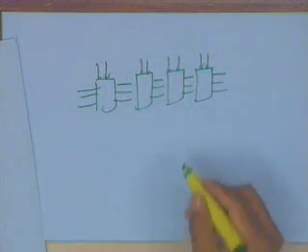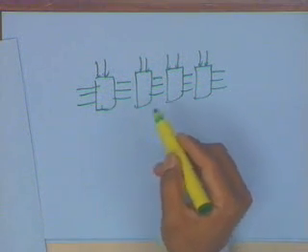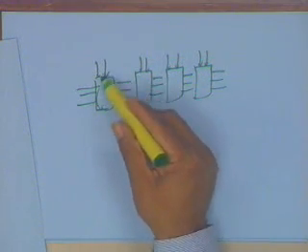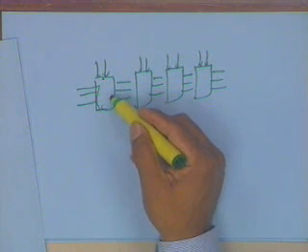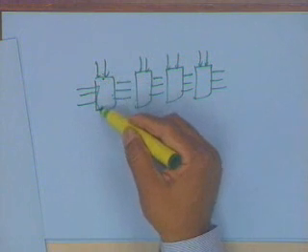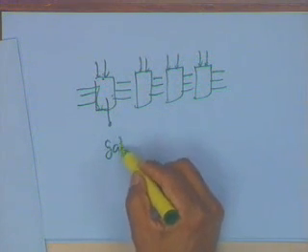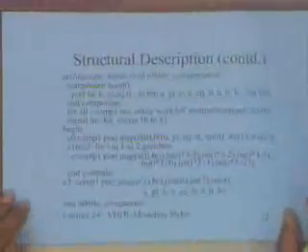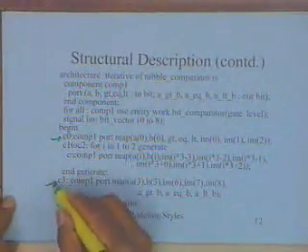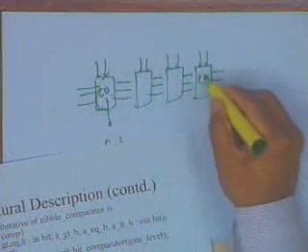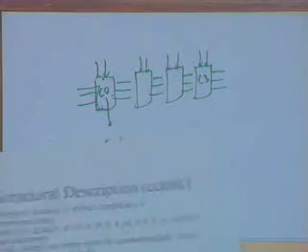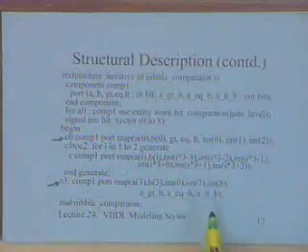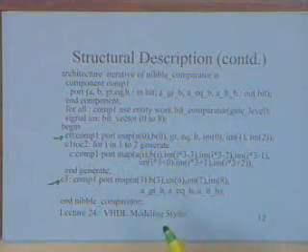This is a 4-bit comparator which is built using 1-bit comparator. So I have described this 1-bit comparator, and I described it not as a structure but as a data flow. I have my choice. I could have described this also as a structure consisting of gates. That's also perfectly valid. Now in this case, as far as C0 and C3 are concerned, C0 and C3 correspond to these configurations. For C0 and C3 I have put different statements, but C1 and C2 I have done through a generate statement.